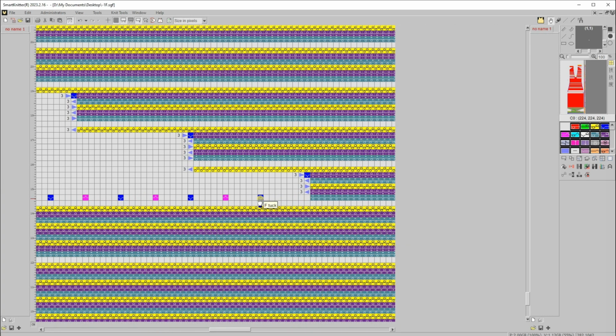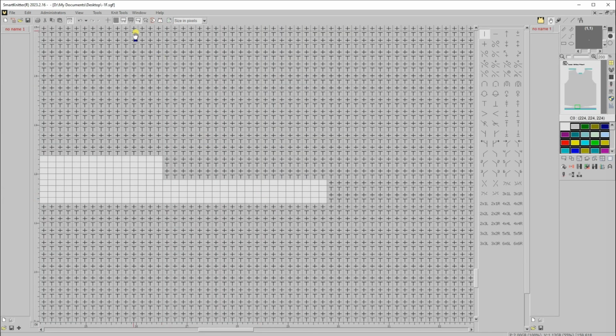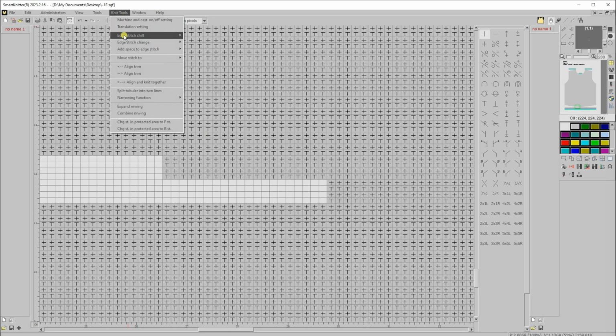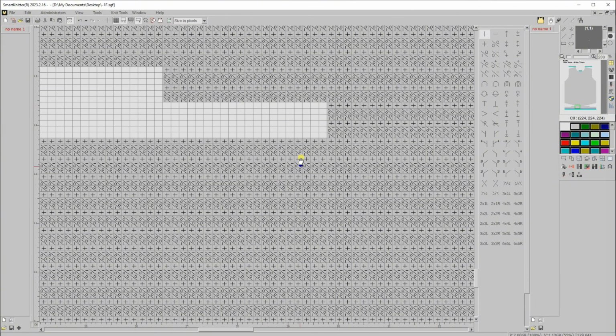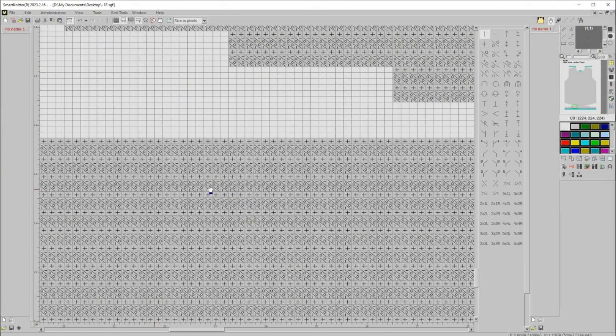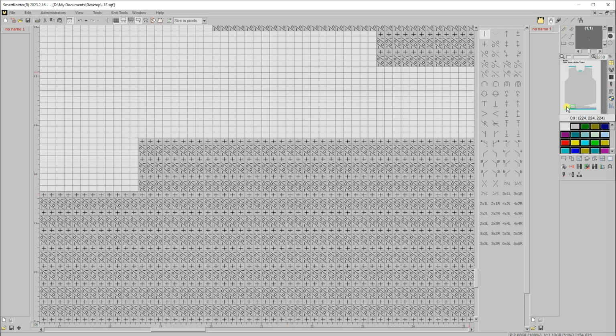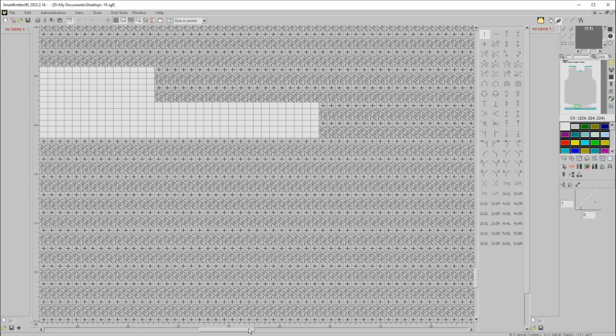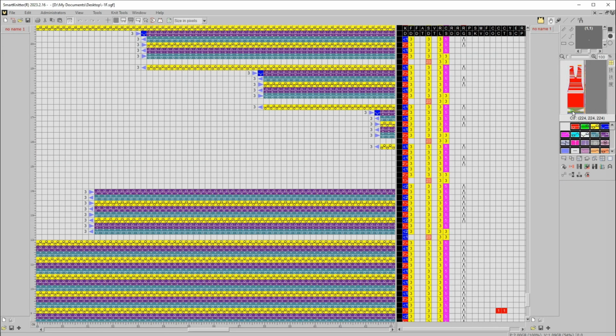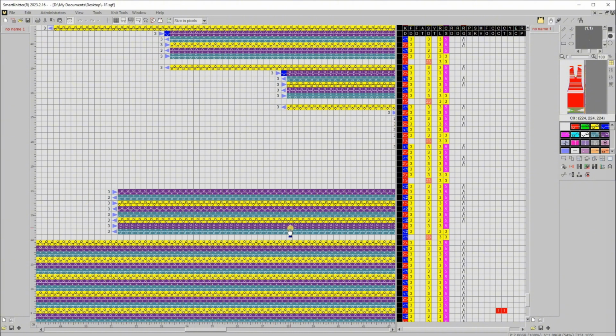In order to solve this problem, we first split the tubular into 2 lines for easier calculation. Select the area and go to Knit Tools, Split Tubular into 2 lines. Tubular in the selected area is now split into 2 lines, front stitch and back stitch. We can now determine the section to edit to correct the carriage direction. Remove the full needle here. The carriage direction is now correct, and there is no extra float.